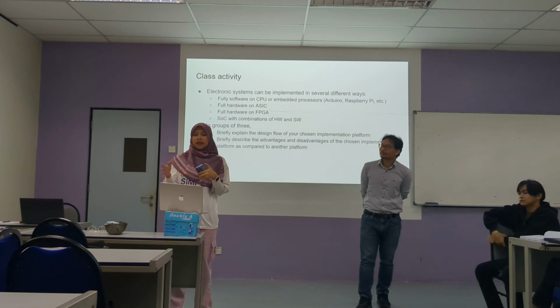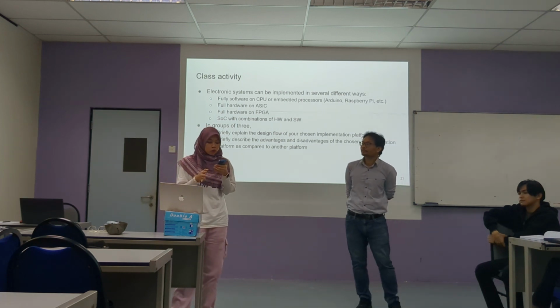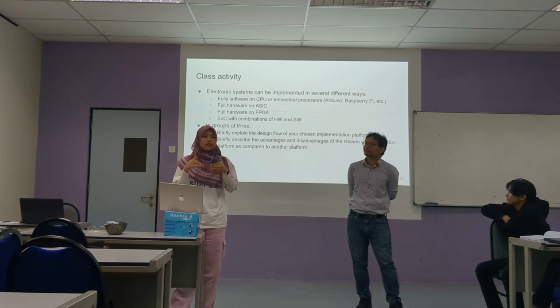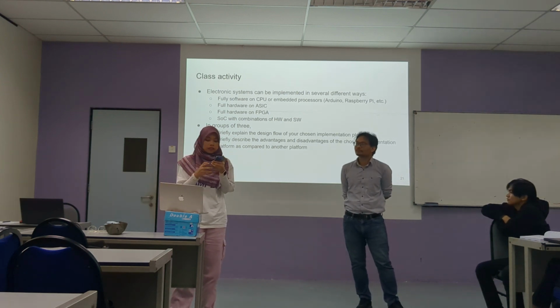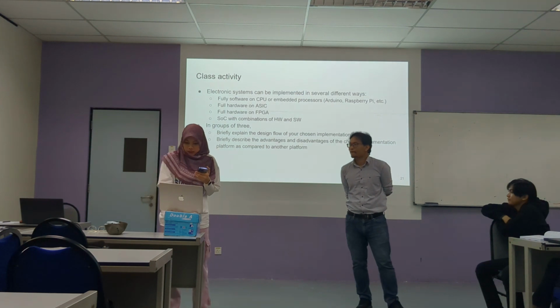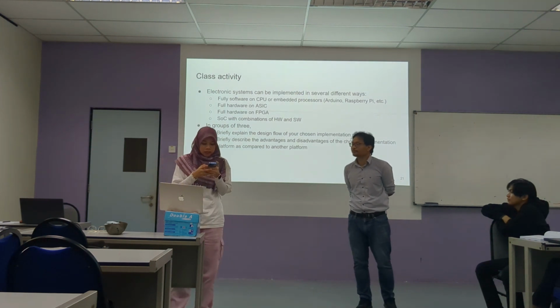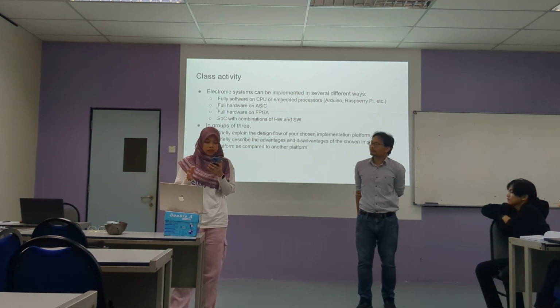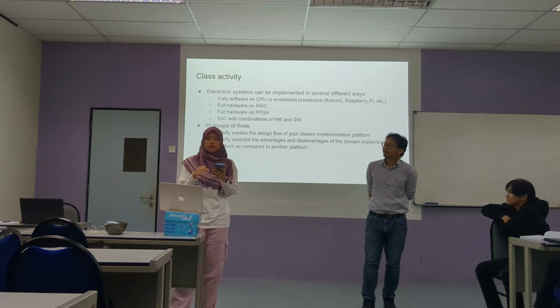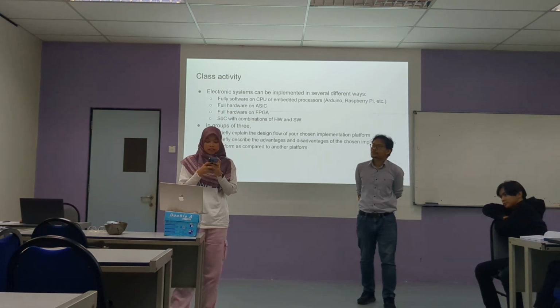Then the second stage is the synthesis. From the high-level design, we need to convert into the netlist of logical elements and interconnections. The next one is the implementation, in which we place and route the logical elements into the physical FPGA device.